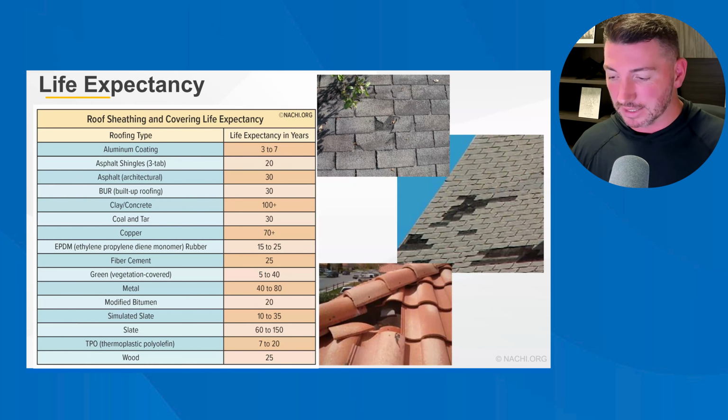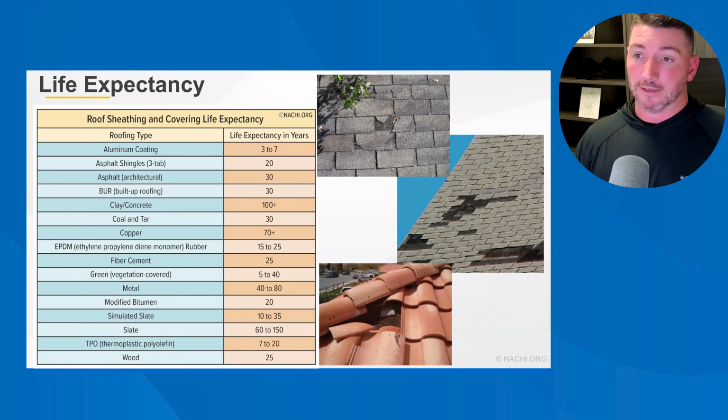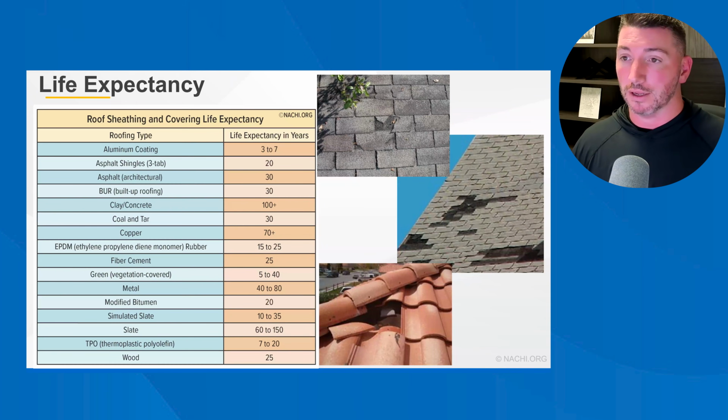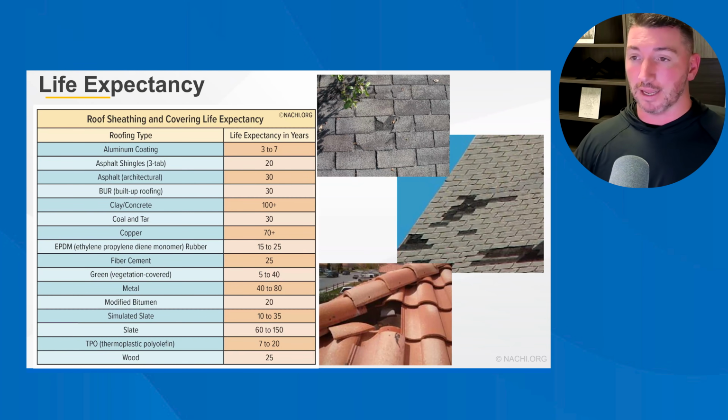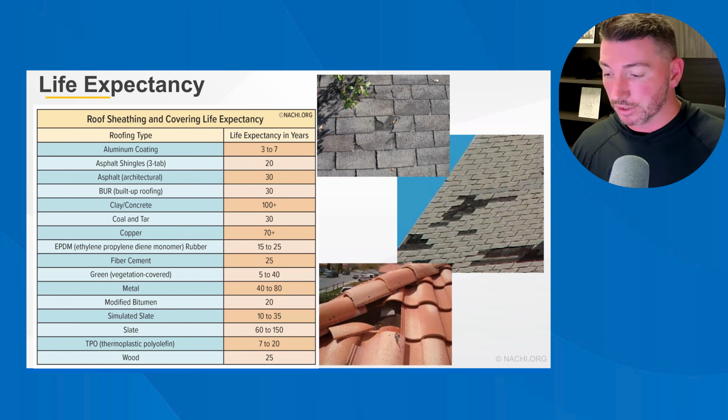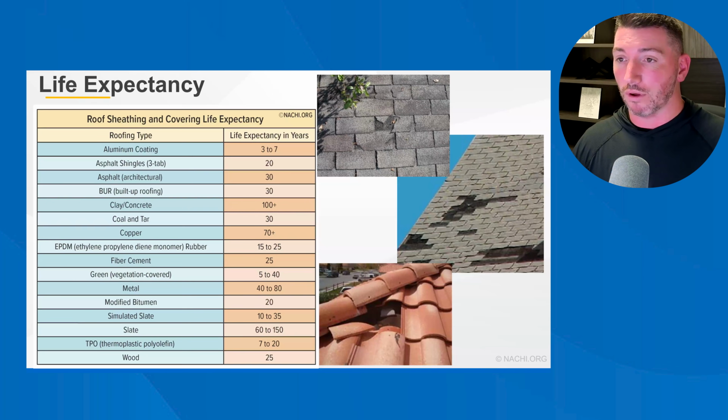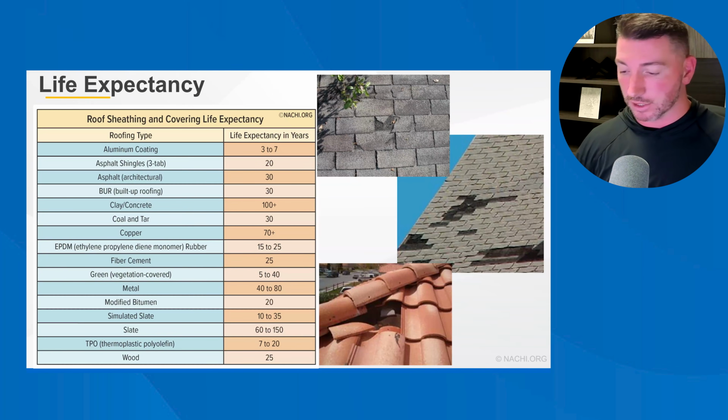Insulation. Inadequately insulated attics will also promote rapid failure of the roof covering due to issues such as ice damming in colder climates. And we can talk about ice damming later, but it's a function of insulation and these other things. And there's a certain amount of, you can't avoid certain parts of it. So that's why building codes, especially north of the Mason-Dixon line, are going to require that you use ice and water shield within 3 feet of the outside wall. So again, if you have a longer overhang, you're going to need to do 2 layers and those kinds of things.